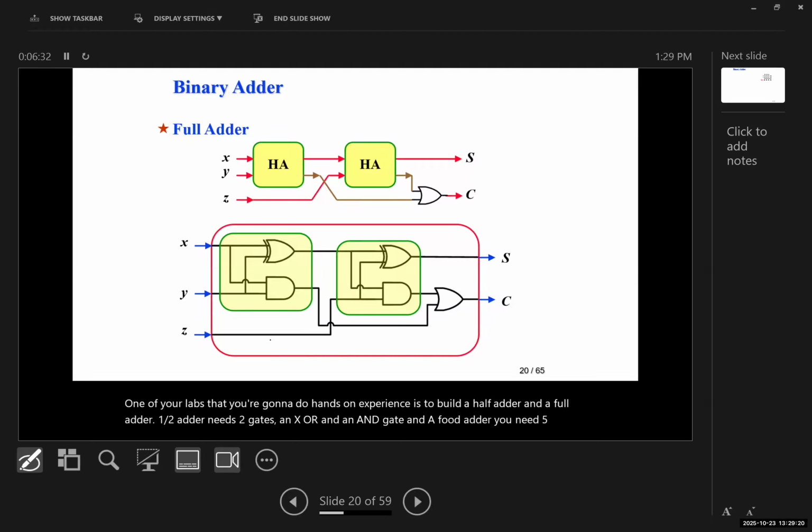Okay, is it clear? I have seen multiple times in the FE exam that they gave a question on full adder and half adder. One time I remember the question is, they will give like 4 different circuits and ask which one is a half adder. If you memorize it, it's easy. If not, you can just simply use a truth table to solve it and see which one gives the correct answer for a full adder or a half adder.